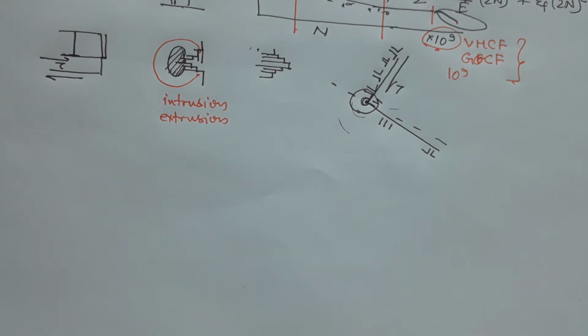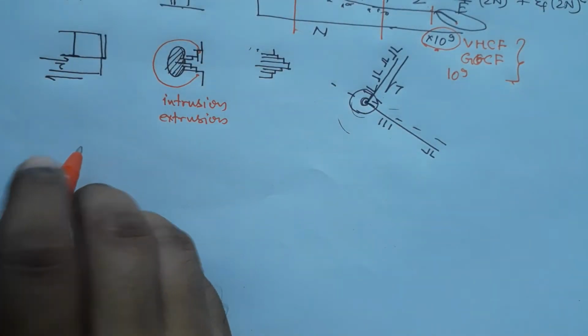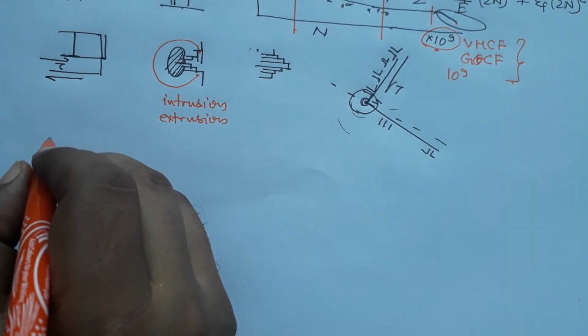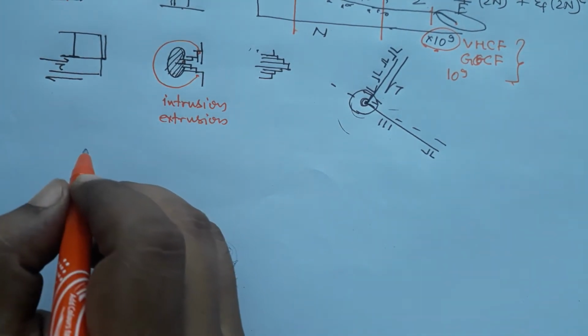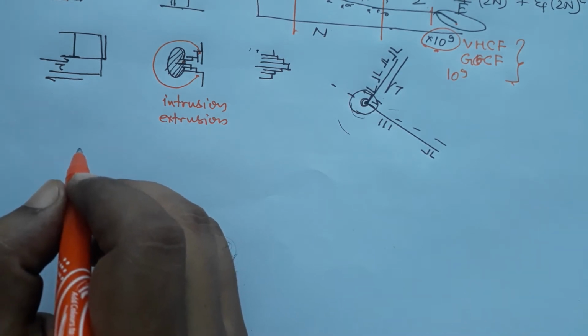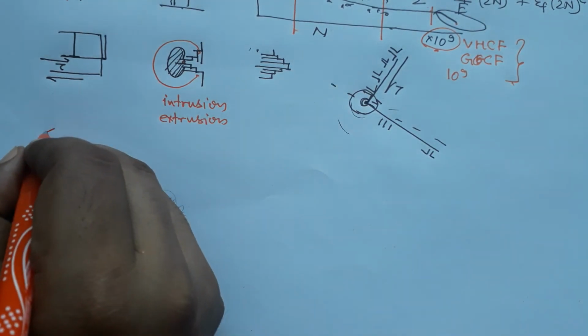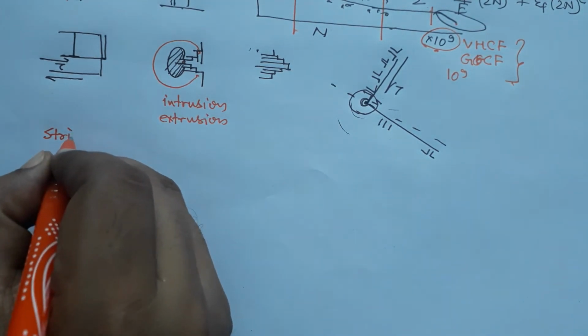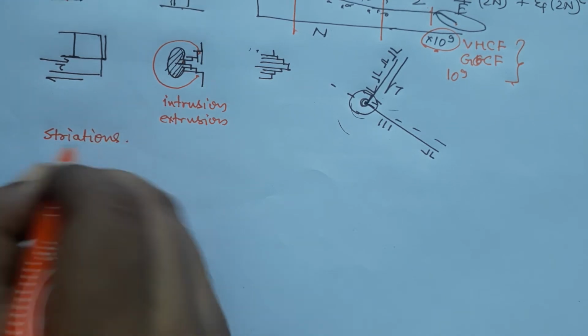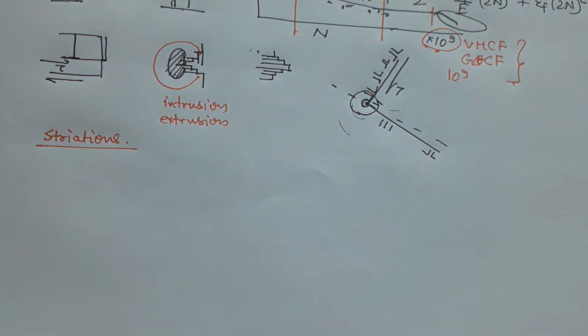So we have discussed in fractography previously that in ductile material you have dimples, and you know why dimples form. In brittle material we see river patterns and tongues, so we know why that forms. In fatigue, the broken specimen will show striations, okay, and striations are visible only in a scanning electron microscope, not by the naked eye.